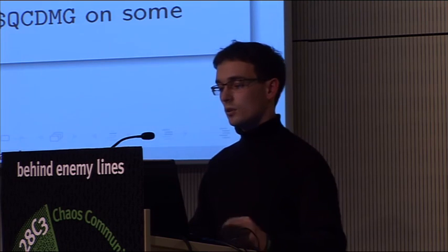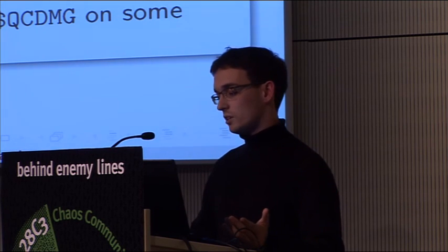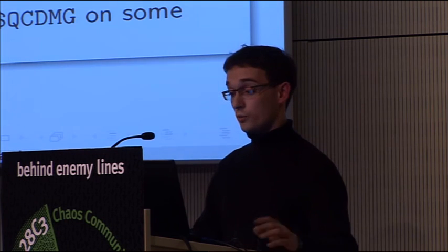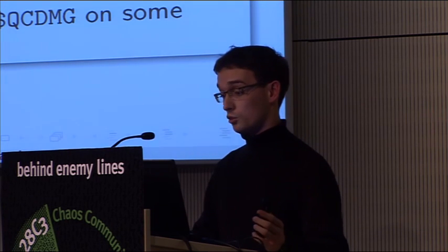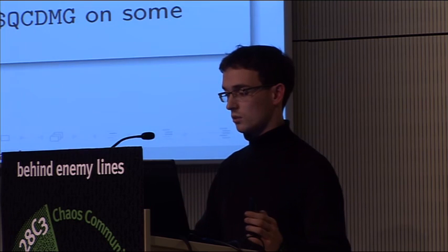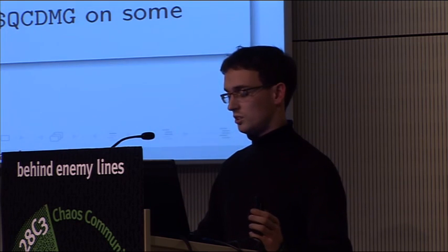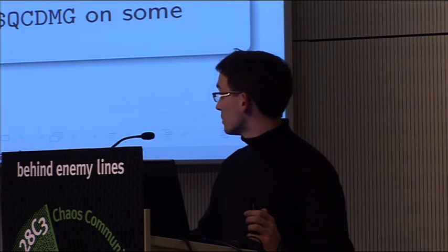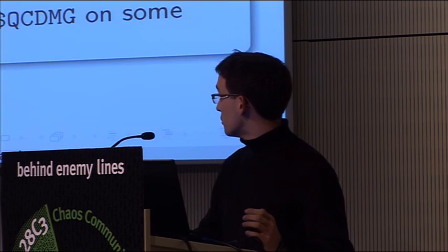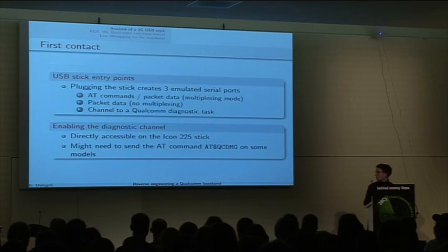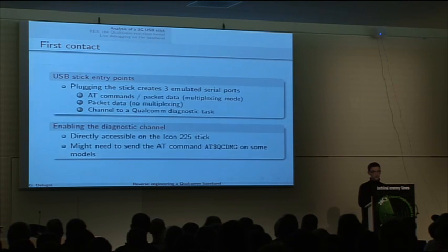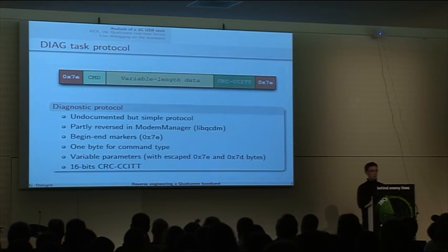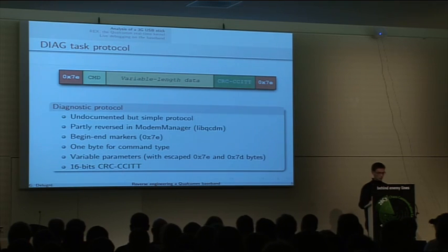So how to enable the diagnostic channel? It's very easy because, on this model, it's directly accessible. You can directly pass commands to the diagnostic mode. On some phones, I've seen you might need to send a strange AT command like AT$QCDMG to activate the diagnostic mode. It's a serial port, so you can pass data into it, but there is a